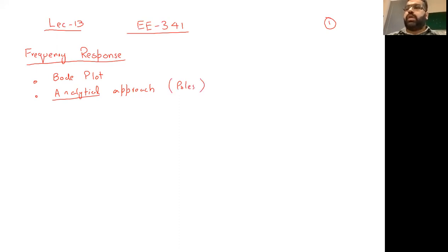If this is a simple circuit, a common source amplifier where the input is here and the output is here at this point, this is VDD, this is an RD, and there's a load capacitance. How can we determine ultimately the pole?